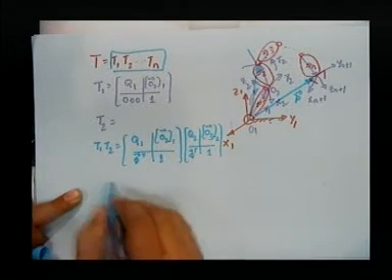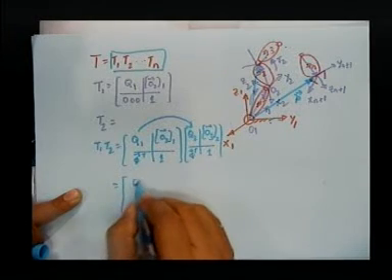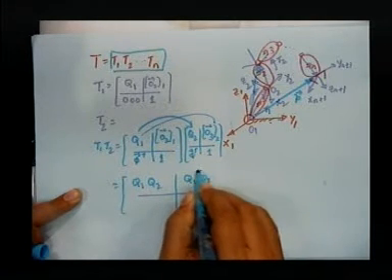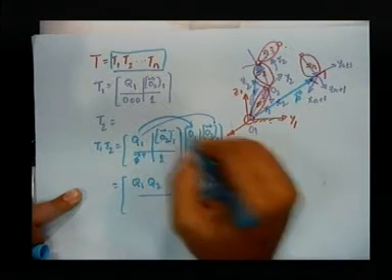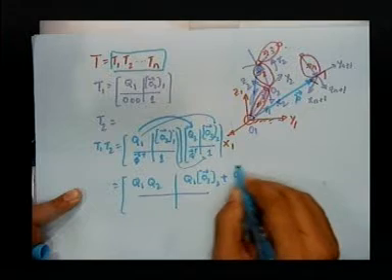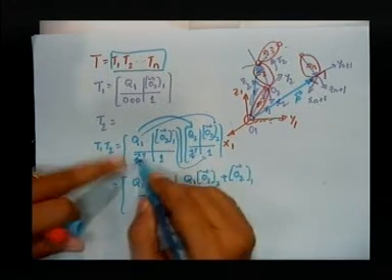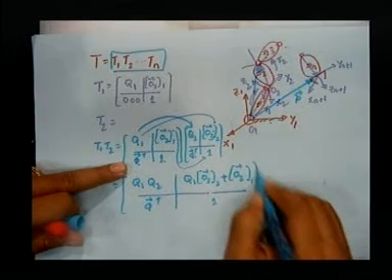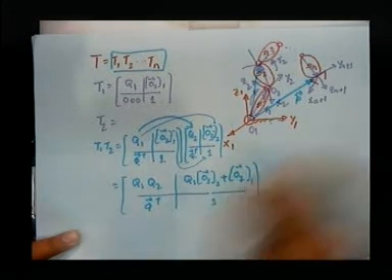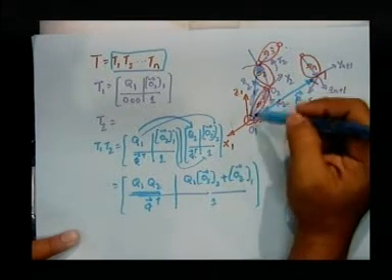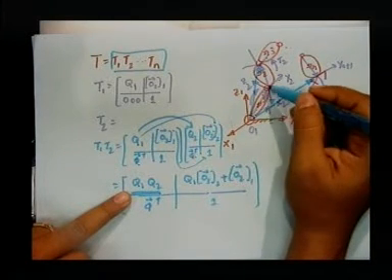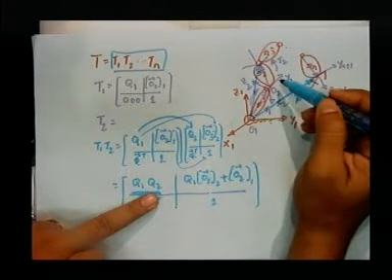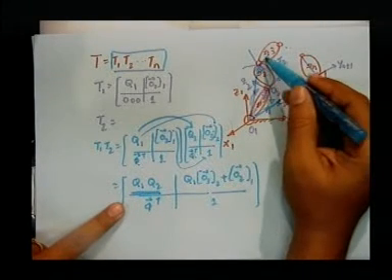So, I am talking about these two bodies, right. Now, if you do the multiplication, this will multiply with this. So, Q1 Q2, then this will multiply with this, so Q1 O3 plus this with this, O2 in 1. Then this with this will be 0, and this with this will be 0. So, this is phi transpose, this and this 0, this and this 1. If you look at T1 into T2, Q1 Q2 is nothing but the multiplication of the rotation matrices. We have learned that Q1 is the orientation of frame 2 with respect to frame 1, and Q2 is the orientation of frame 3 with respect to frame 2. When we multiply, we will get the orientation of frame 3 with respect to frame 1.